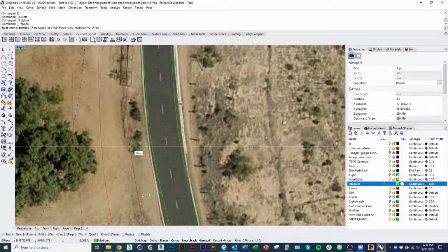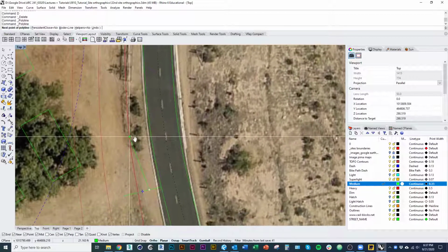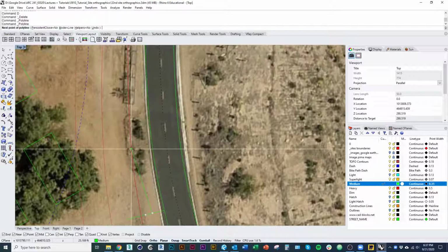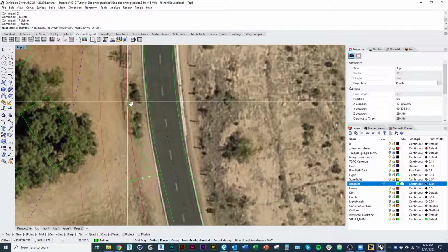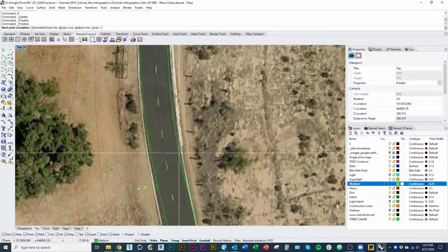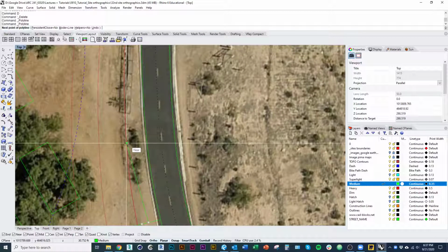And I know that I want about 20 feet of ramp, between 12 and 20 feet of ramp for every foot of elevation change, right? That's our ADA ratio. Because it's a 2-foot drop, I'll just assume it's a 2-foot drop from the path. I'm going to go for something between 24 and 40 feet. I'll just do like 30. Good.